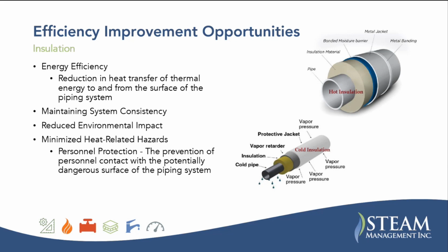A reduction in heat transfer of about 90% can be expected from a good insulation job compared to bare surfaces. It also helps maintain system consistency. Again, you're reducing your carbon footprint, and you are also creating a safer environment for your workers by minimizing heat-related hazards.